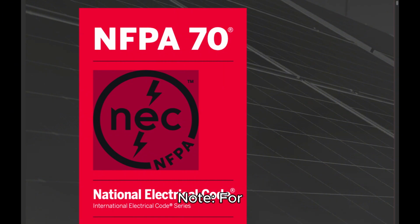Informational note: For motors, see 430.232 and 430.233. For over 1000 volts, see 110.34. 110.28 Enclosure types. Enclosures other than surrounding fences or walls covered in 110.31 of switchboards, switchgear, panelboards, industrial control panels, motor control centers, meter sockets,